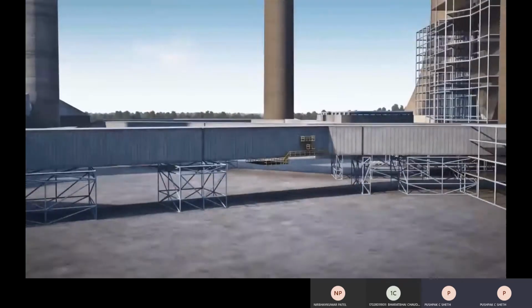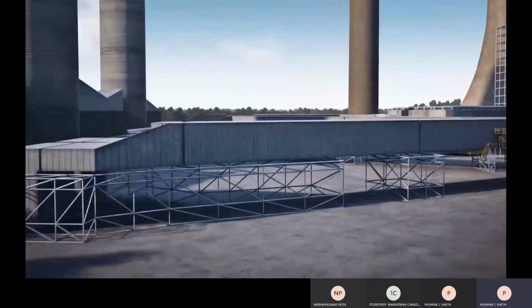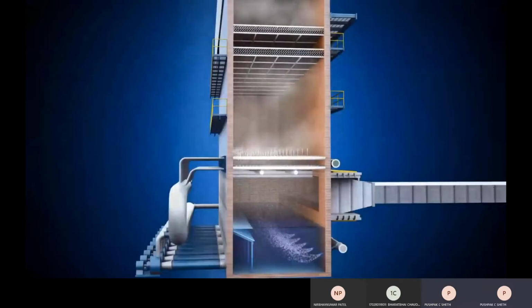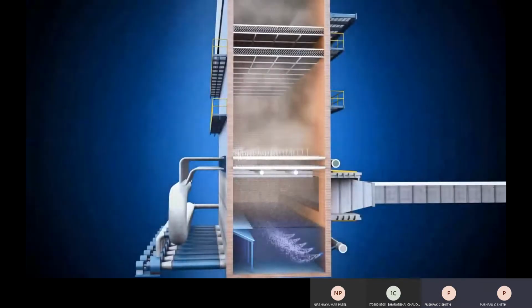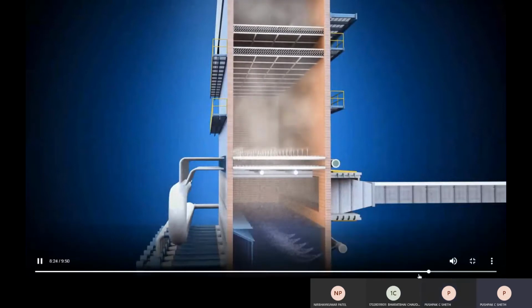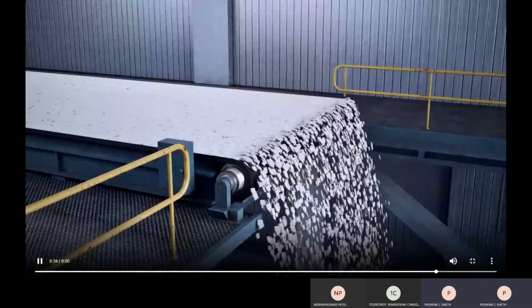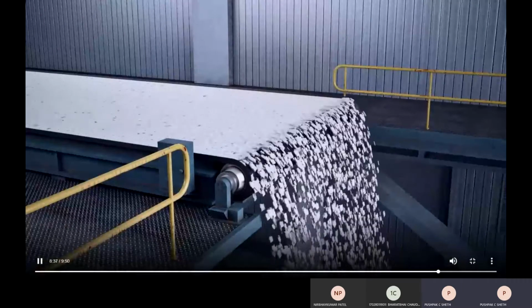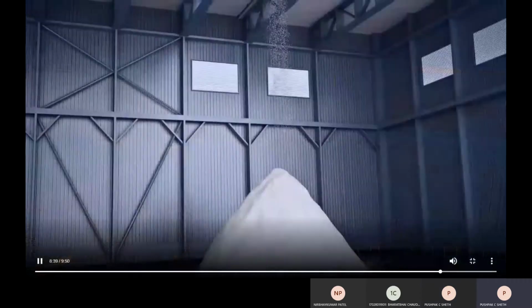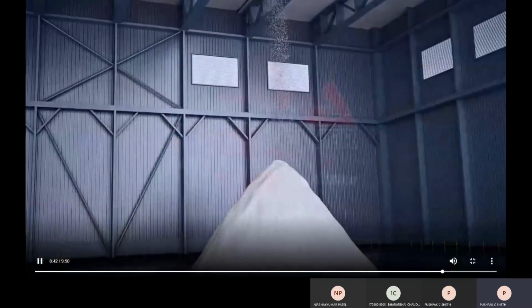The gas then passes through the induced draft fans into the scrubber, where booster fans pull the flue gas from the plant and push it through the scrubber absorber. In the absorber, flue gas mixes with water and limestone. The limestone reacts, removing 90% of sulfur dioxide and creating a byproduct of gypsum. The wet flue gas exits out the top of the absorber through to the wet stack, and a gypsum stream is pulled from the bottom of the absorber and sent to a dewatering facility. There, most of the moisture is removed from the gypsum so it can be sold for use in wallboard.